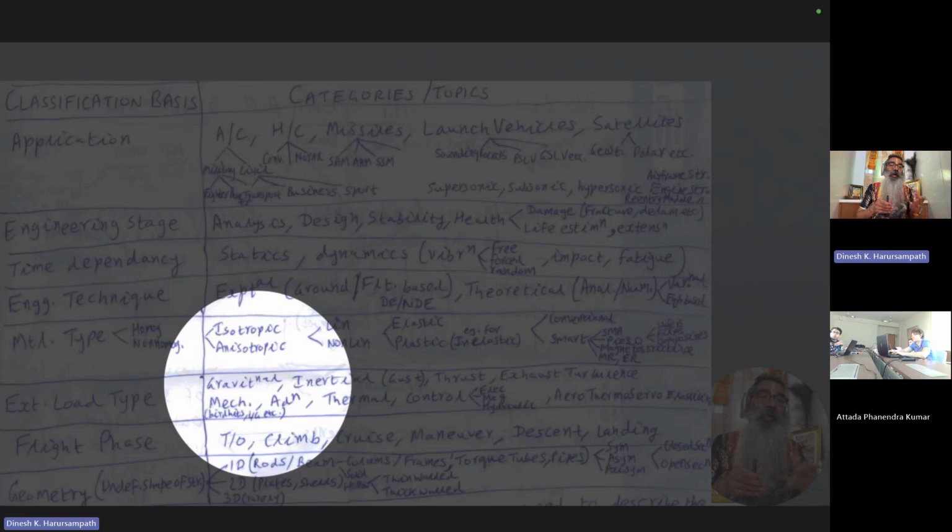And this will be kind of handy for your second assignment as well. You will see that though most places it's composites and many places it is aluminum or titanium alloys, especially for military aircraft, you will see that steel is also continued to be used in some very rare, exceptional places. And one such example is the landing gear, because absolute values are important there more than just these specific values. So we're willing to go with some weight penalty in some of those locations.